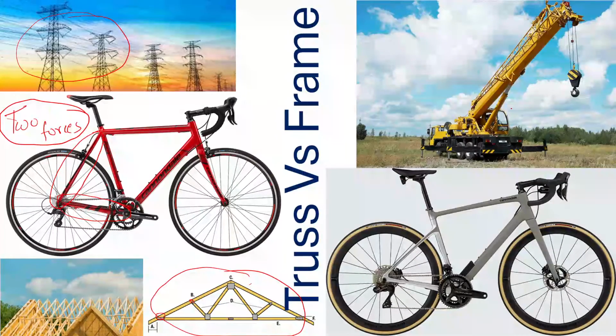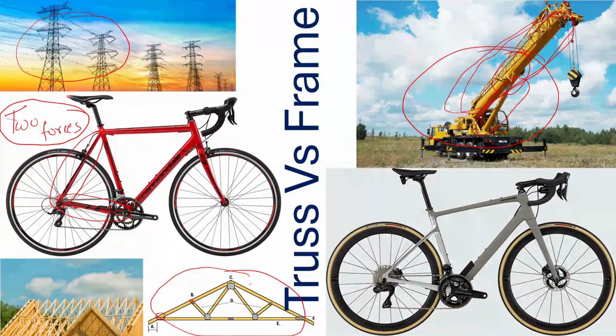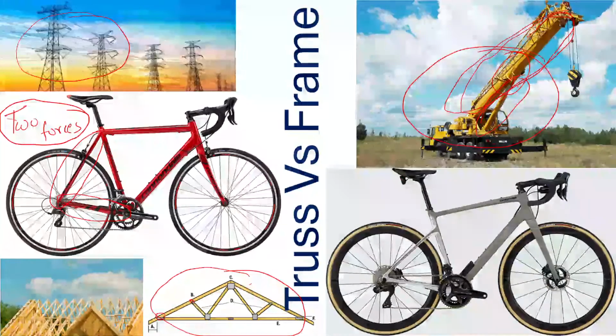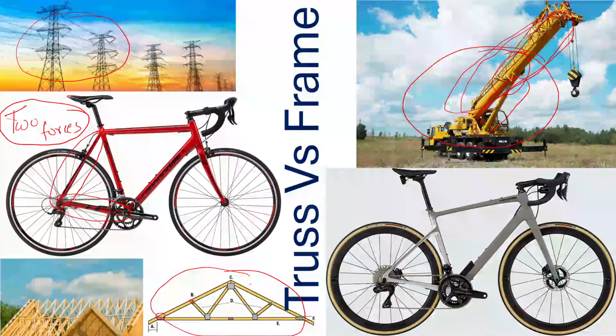However, if you look at this crane on the right corner, this boom arm is lifted up and down by this cylinder right here. So this cylinder pushes up and down. So this boom does not necessarily face much tension or compression. It actually faces some kind of shear force and bending moment, which we'll discuss later in the mechanics of materials chapters. And it's not a triangular arrangement.